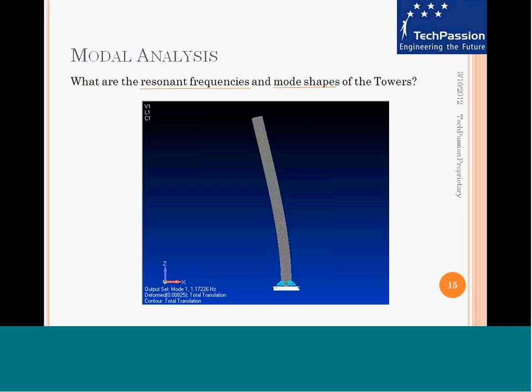We did modal analysis of this tube. Here when you do modal analysis, the structure is different. In the last case we were looking at a geometry which is rectangular in cross section. Here we are looking at a tubular cross section. What I am showing here is the first mode. In addition to this, when we look at the higher modes, since it's a tube, you get the breathing modes of the tube. We are not so much interested in those modes, so let's focus on just the first fundamental mode of this structure.